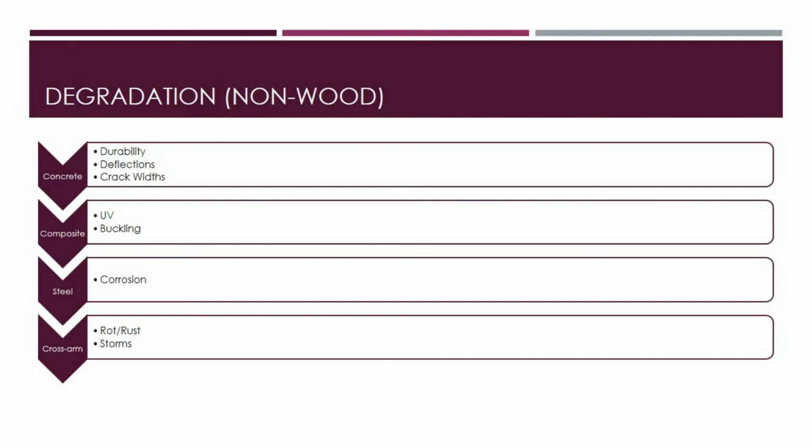Steel poles deteriorate owing to corrosion beneath the surface or problems with the coating. And as a result, the most effective method of evaluating below-grade degradation is to excavate a portion of the surrounding soil to conduct a visual assessment.